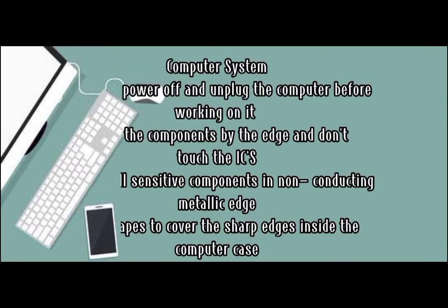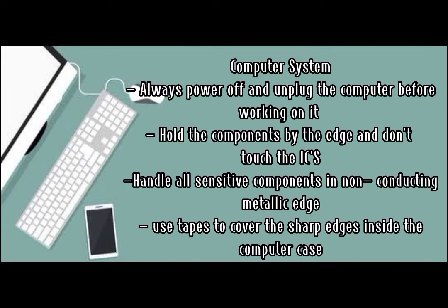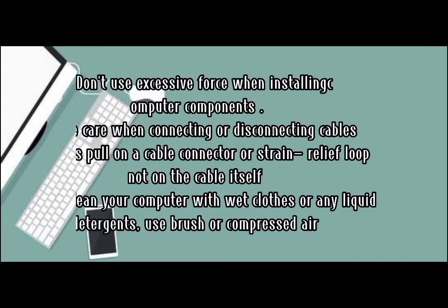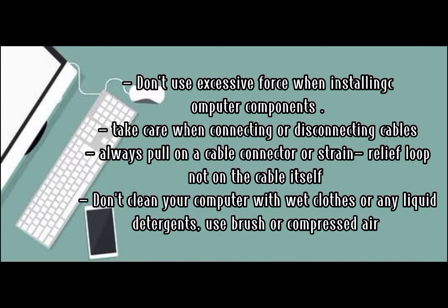The second one is the OHS for the computer system. Always power off and unplug the computer before working on it. Hold the components by the edge and do not touch the ICs. Handle all sensitive components by the non-conducting edge to avoid electric circuits. Be careful and use tape to cover the sharp edges inside the computer case. Do not use excessive force when installing computer components to prevent damage.